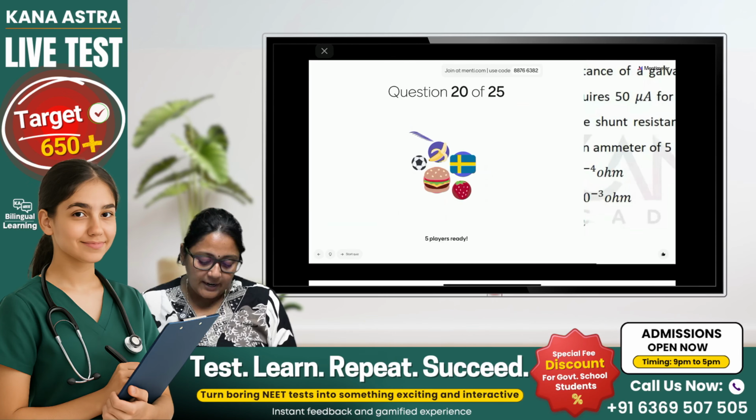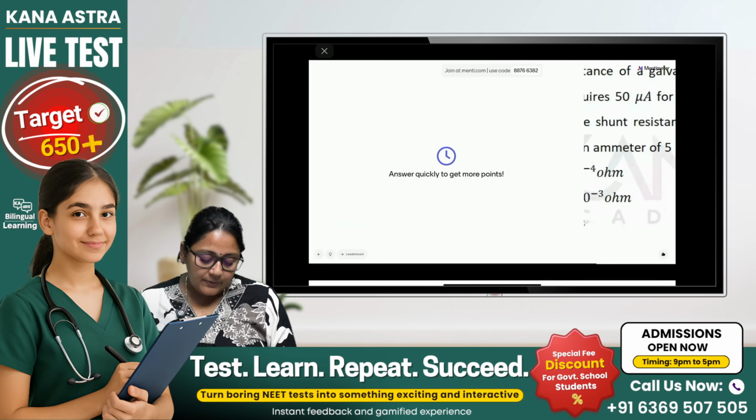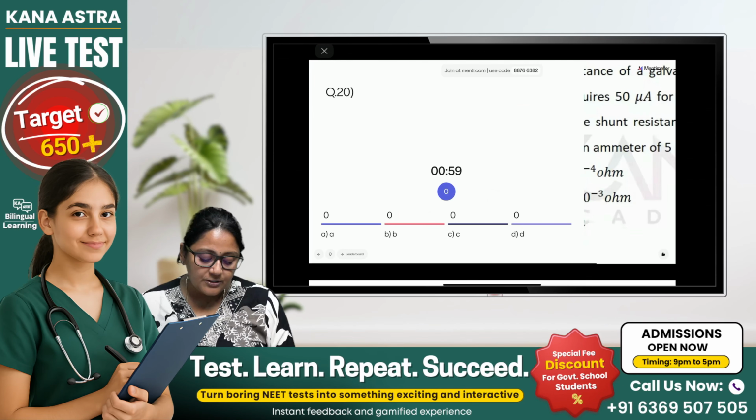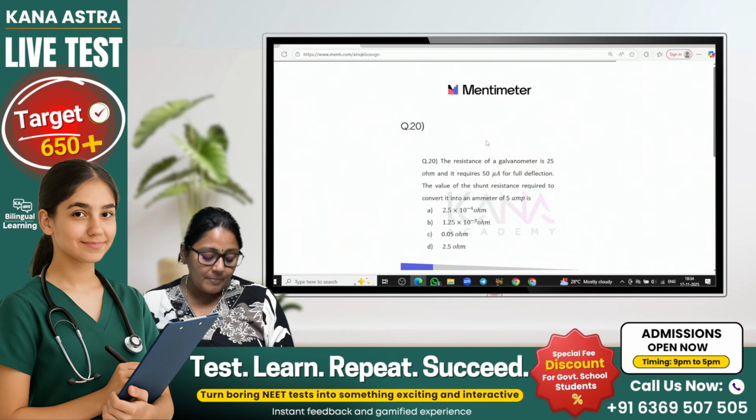The next question is, the resistance of a galvanometer is 25 ohms and it requires 50 microamps for full deflection. The value of the shunt resistance required to convert it to an ammeter of 5 amp is, what shunt resistance is required, they are asking. So the options are 2.5 into 10 to the power of minus 4 ohms, 1.25 into 10 to the power of minus 3 ohms, 0.05 ohms, and 0.25 ohms. Sorry, 2.5 ohms, option D.